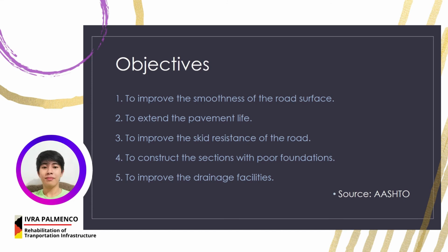And lastly, number 5, to improve the drainage facilities. Poor drainage is a traffic safety risk. Water may accumulate on the road like ponds, and accumulated water creates a risk of aquaplaning during rain. A wet surface also reduces friction, which leads to longer braking distances. So, existing drainage networks should be cleaned regularly and extended to receive the maximum flow rate if possible, and proper maintenance of the drains and drainage system can prevent clogging and other unwanted effects.